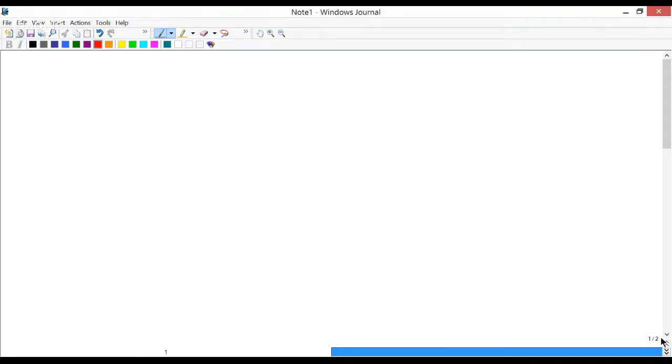Going back to assignment 2, question 6: weld time of resistance spot welding is directly proportional to the thickness of the sheet. The higher the thickness, the longer you need to weld because of the mass effect I told you about in class. Question 7: in full interface failure of a resistance spot weld, the plug ratio is 0. Because what is a full interface failure? We just open the weld as it was before welding. The plug ratio is the plug size upon testing divided by the weld nugget diameter. If there is no plug, if the size is 0, obviously the plug ratio becomes 0.